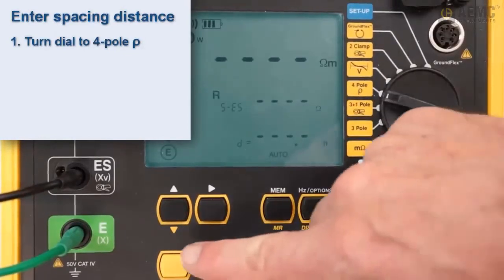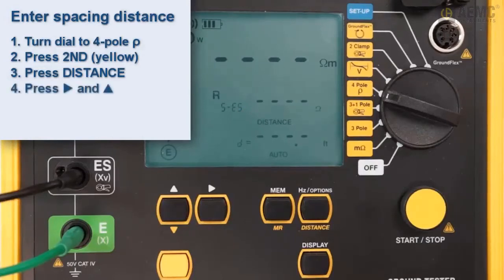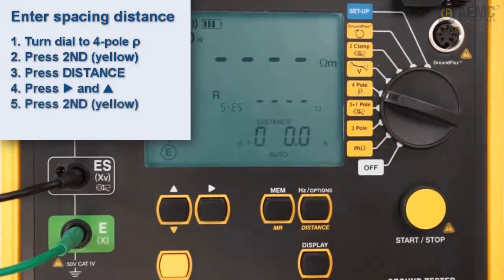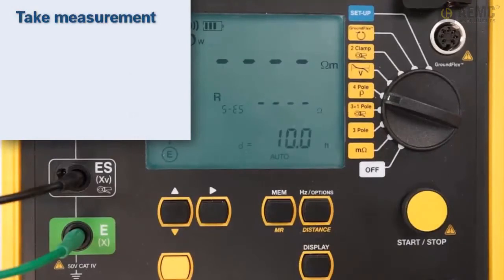To enter the spacing distance, press the yellow button, labeled second. The symbol second appears on the screen, indicating the buttons will now perform the actions labeled in yellow. Press the distance button. The word distance appears on the screen, and the first digit in the distance field blinks, indicating it is in edit mode. Use the up and right buttons to navigate through this field and make selections. For example, to set the distance to 10 feet, press the right button to navigate to the second digit and press the up button to change this to 1. The field now should be set to 10 feet. You can save the setting by pressing the yellow button to enter second mode, then pressing the distance button. You are now ready to take a soil resistivity measurement.